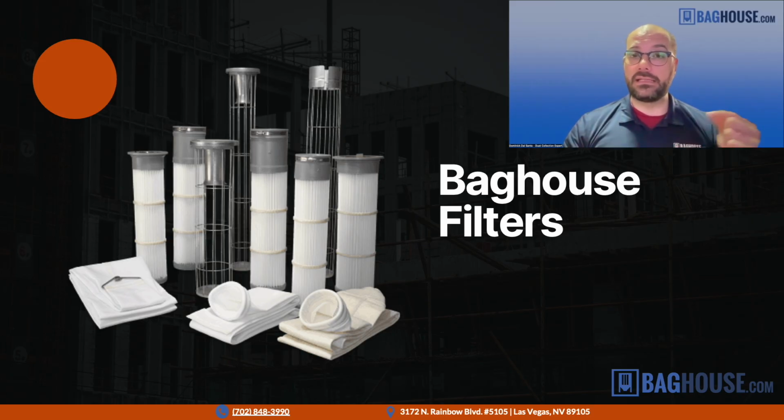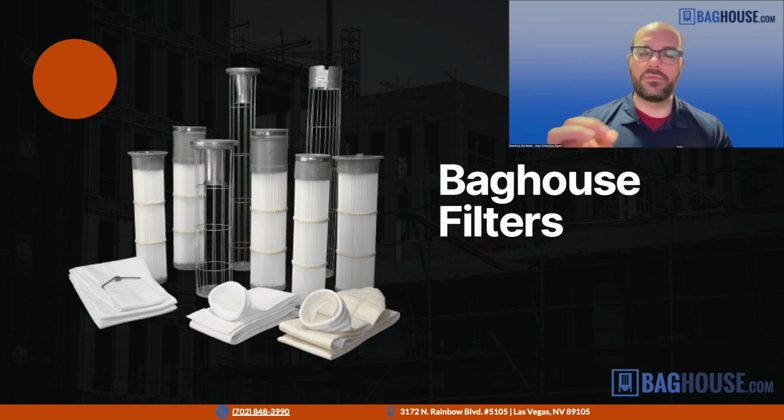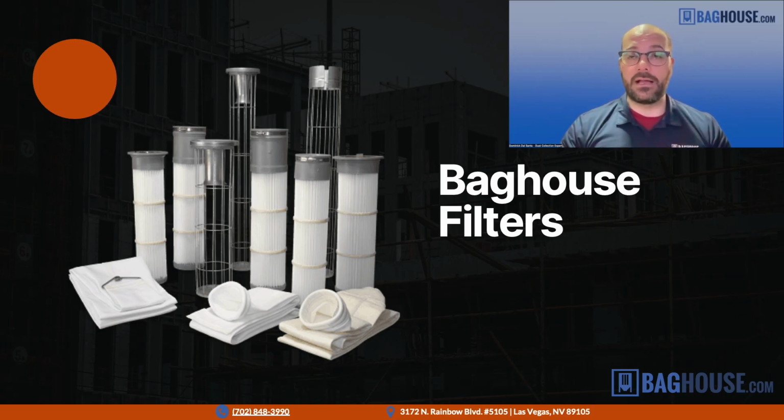This is different from PTFE filters, where the bag is made out of the PTFE. And it's not just a spray coating, which unfortunately we've seen some manufacturers start promoting the same way. PTFE membrane is a separate filter material that's made and then laminated to the surface of the filter bags. And it has the effect of capturing more of the smaller particles and allowing for the dust to release more easily. So these are just a few of the common filter medias you'll see in the baghouses.